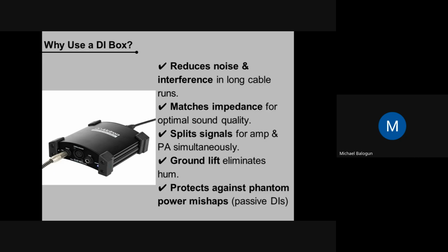If there is a leakage somewhere, there is nothing you can do except discontinue the use of that microphone and trace the fault. We've experienced it around here. You trace the fault because it's dangerous. We've had a situation where someone used the mic and felt it shocking on their lips. So you discontinue it immediately. Safety first.